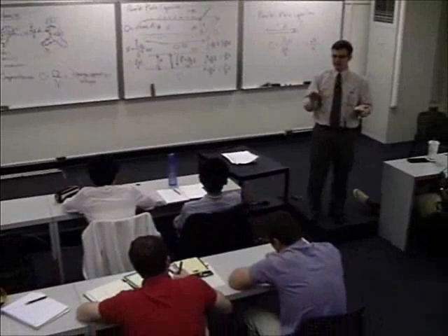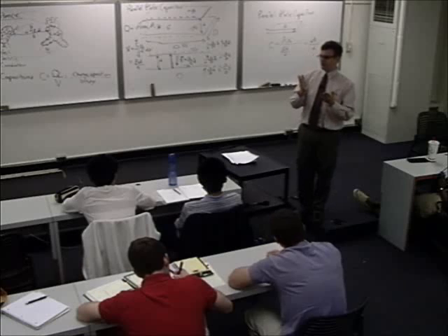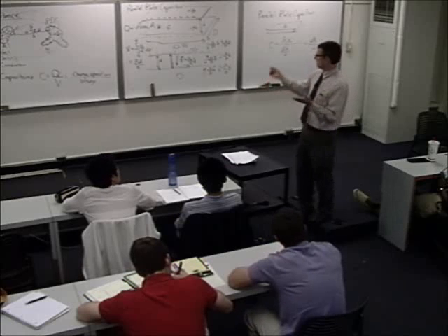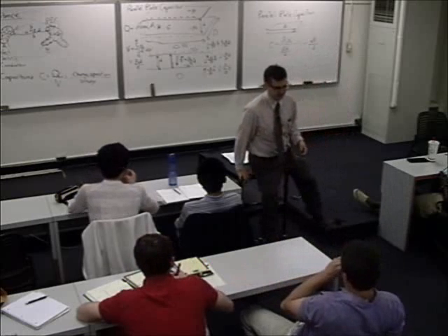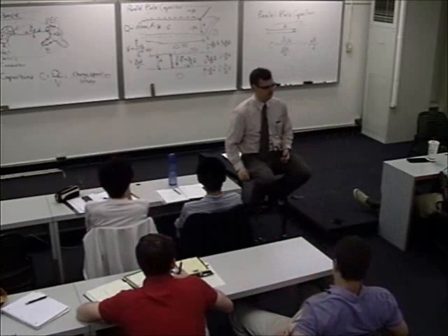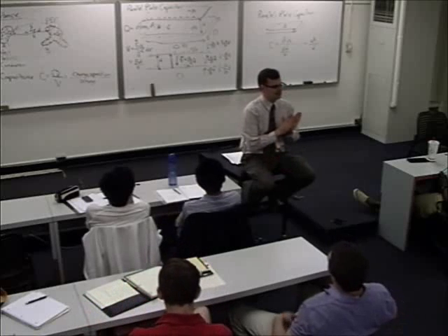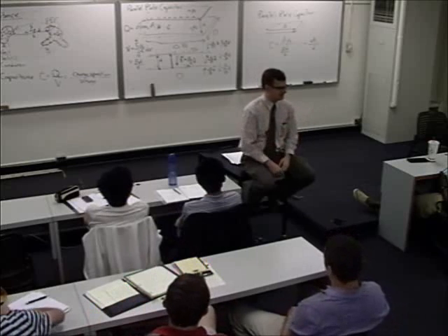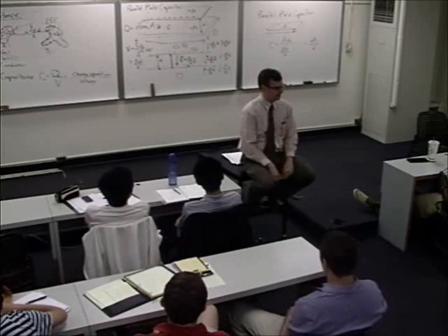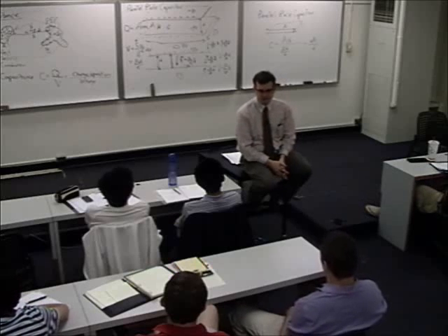Usually, for those cheapy capacitors that you're using in 3041 or 3042, they're just paper dielectric. So the epsilon is not very large. Epsilon is like 1 point something. You'll be lucky to get 2. Maybe some of them use some plastic, some Teflon or some polypropylene, or anything that insulates that you can make really thin. And you take those 2 plates and you press it over.